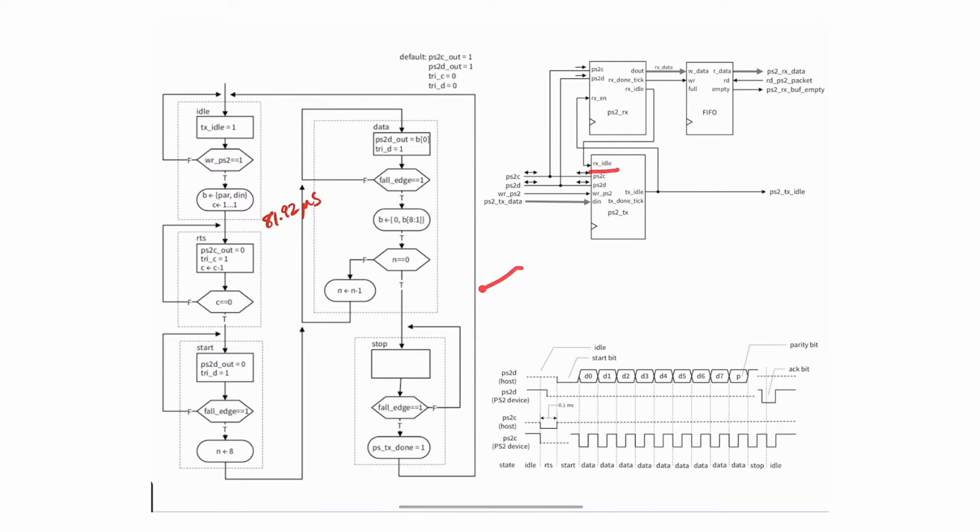If you take a look at this finite state machine, it does not utilize this Rx idle because it's in that little hidden state. The reason, again, is that it is not shown in here. The purpose is just to make sure that the receiver is not receiving anything. You should not be sending in the middle of the receiver receiving a byte. If the receiver is on byte 5 out of 8 or whatever, just wait for it to finish. When it finishes, now you can send whatever you want, and you take control of that bus. Anyway, we continue in here.